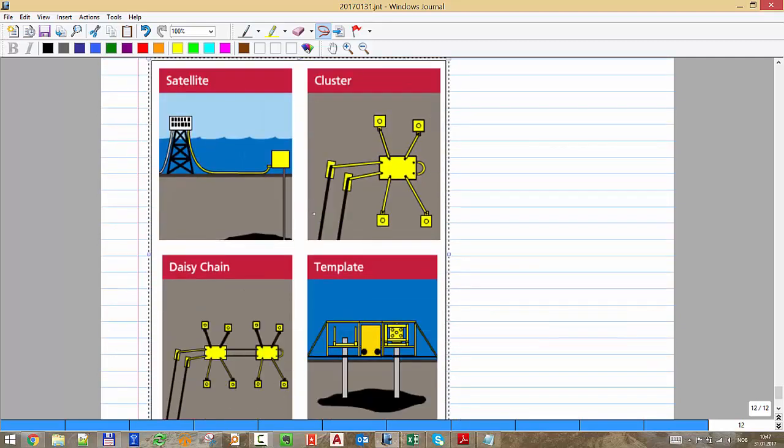In that case you can have one well. If you don't need to execute any pigging and the distance is very short, you can send it directly to the platform, and you put the manifold in the platform to route to test separator A or B. This is another approach, but in this case the wells are outside the template. Here you have the manifold. This is what they call the Christmas tree, or the well template, and you have a manifold template. That's typical, for example, in offshore Angola and offshore Congo. That's an arrangement they use very much.